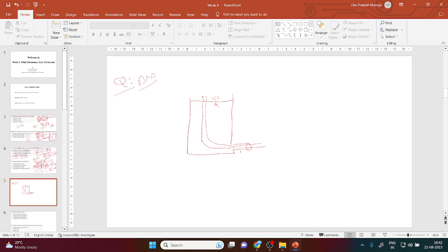Since there is no flow generation inside the tank, in the practical way it should be unsteady flow. Yes, in the practical way, this is unsteady flow. But for solving the question, people assume this is steady flow. But in the practical case, when you go for the real situation, it is not steady flow. Just for the sake of understanding, people frame the question like that. The assumption is already given: the flow is steady, not unsteady.